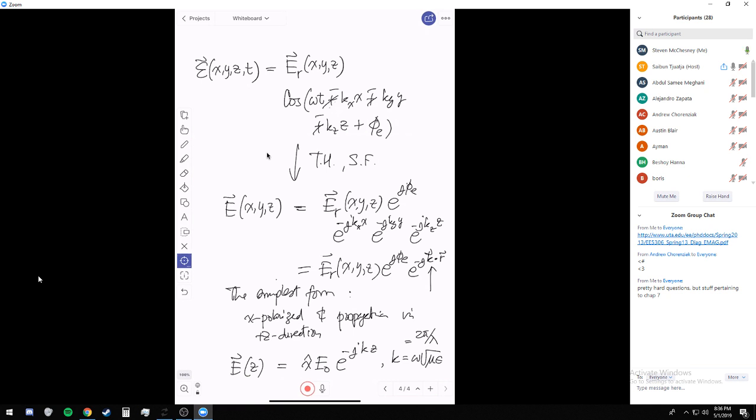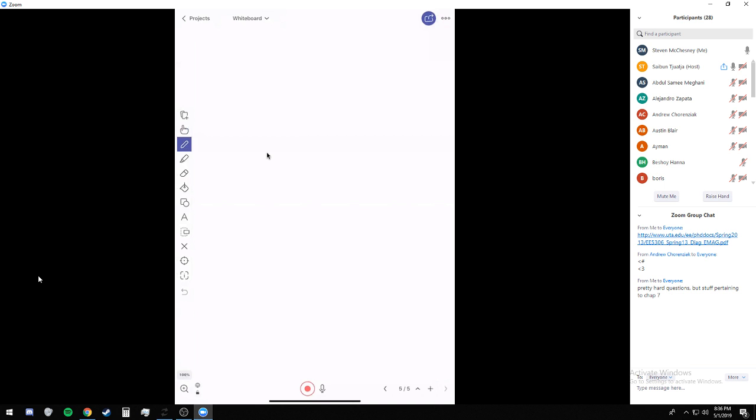I'm sorry. Okay, time average power. Let's take a look at this particular example right here. Suppose you are given the time harmonic form. So I give you this, and when you see this, what comes to mind immediately? Well, this electric field is a function of z, so it changes with z. Therefore, just by looking at this, you know that it's going to be propagating in the z direction. It doesn't change in any other direction, so in this case it should be a plane wave.